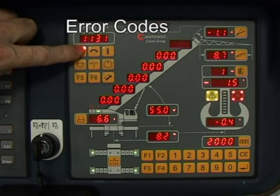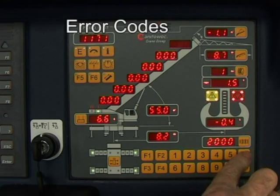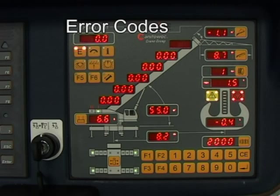Repeatedly pressing the button will cycle all error codes that may exist. The 4-digit error code comprises 3 different numbers. From left to right, our example shows 1 as the error group, 17 as the component, 1 as the type of error. You can acknowledge an error by pressing the CE button.